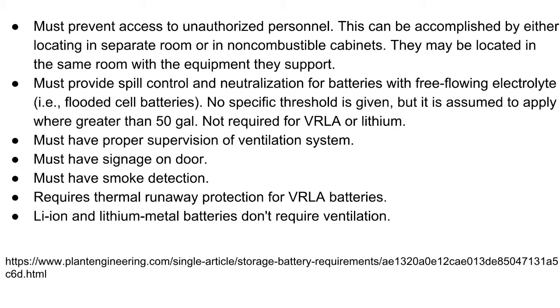On your more expensive battery inverters, it's not just an alarm. It actually will adjust the settings on the battery inverters so that they will operate and run your battery differently. We'll learn about temperature considerations for batteries, and we'll learn that in freezing conditions, you don't want to discharge your battery more than 50%. And then under hot temperatures, they actually gain a little bit of storage capacity. So the temperature sensor can provide additional functionality than just making sure that the batteries aren't overheating.